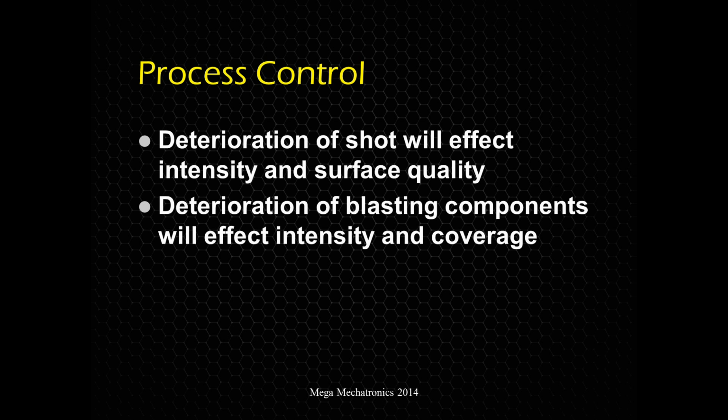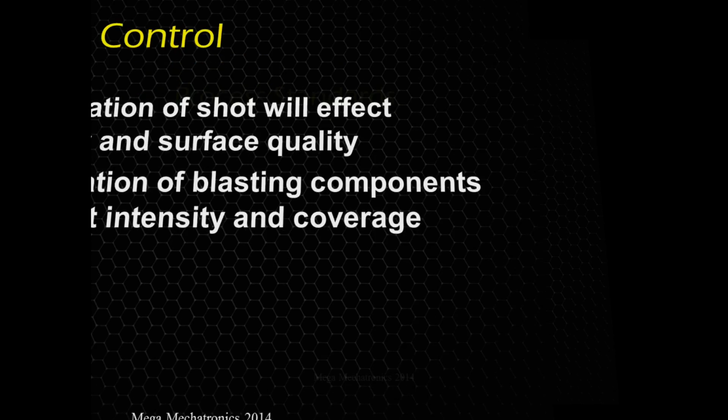And the blasting system. So the nozzles are going to wear out. And that's going to change your flow. And that's going to change your velocities. And the blast wheels wearing out. The paddles are going to get smaller, and the tip speeds are going to be off. Not to mention vibrating like crazy.